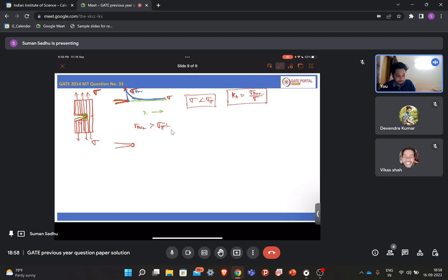Now if this sigma max is way too high, if it even crosses your sigma fracture value, then what will happen? Then a crack will generate again because it will fracture this localized region. So your tip will be very sharp again. Again your tip will get blunted, and again it will get sharp. Like this your crack will propagate. This is the way your crack will propagate.